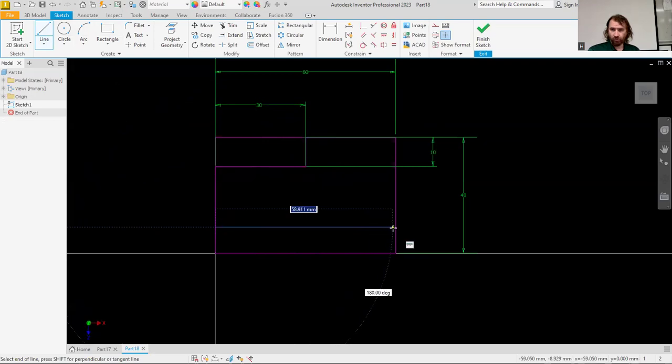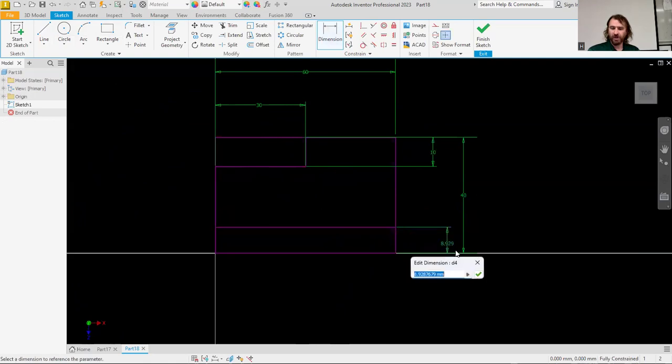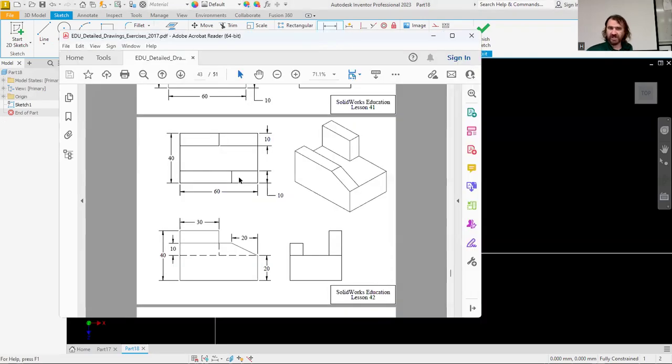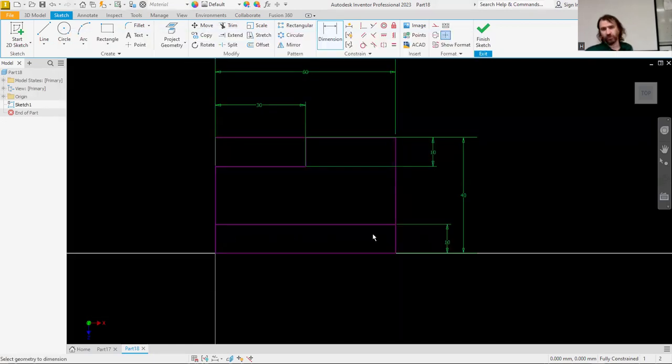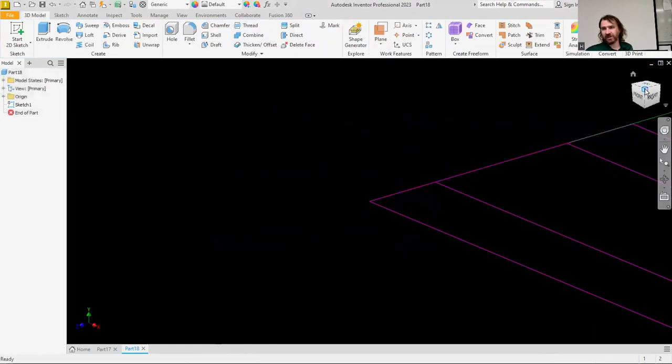And the reason why we just need one profile down here segmented off is because of that chamfered part. From the top view, it looks like a separate rectangle here than it is here, but it's not needing to be drawn. And you can see that here. If we pull the drawing over again, it has this separate rectangle profile here with this line, but that's the chamfer. So we can actually ignore that and just draw the one line to separate out the wall rectangle profile here. And now we can extrude these.